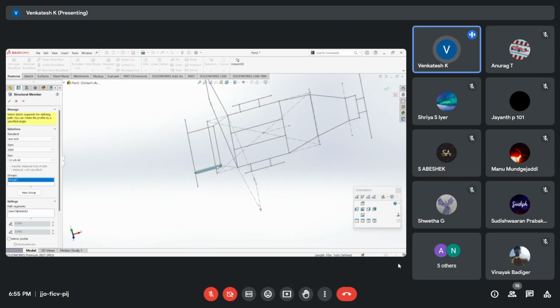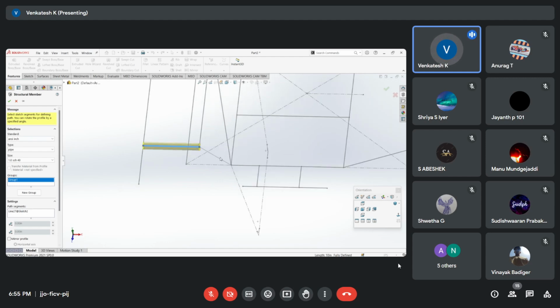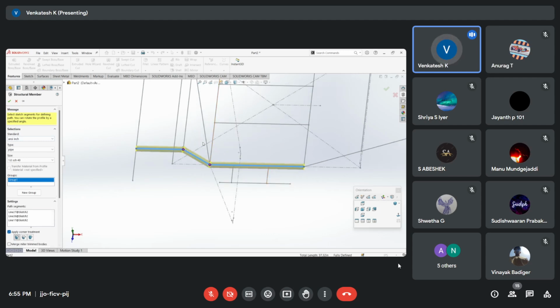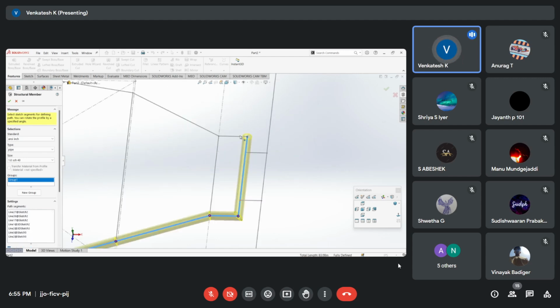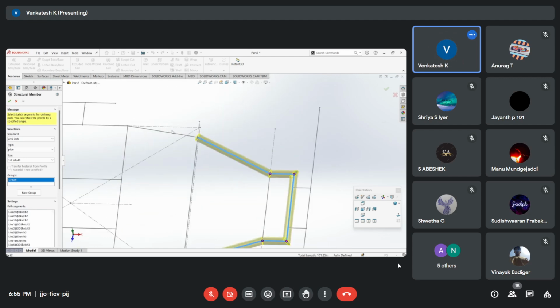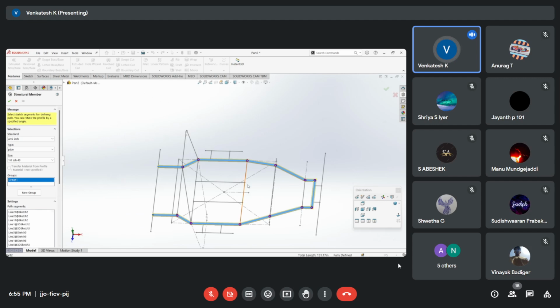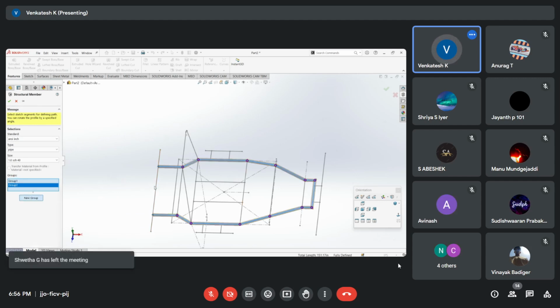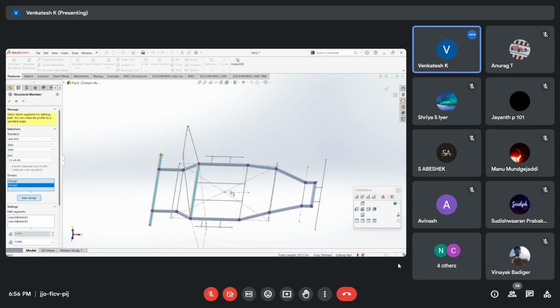In this Weldments tool of Structural Member, you need to go along the loop. You can't start with this loop and go to the next loop at once. You need to take it as a new group. See, this full thing will be a single loop. This is the single loop. This will be a single loop. Then you go to a new group. All the vertical ones, and all the horizontal ones also, can be a single group.